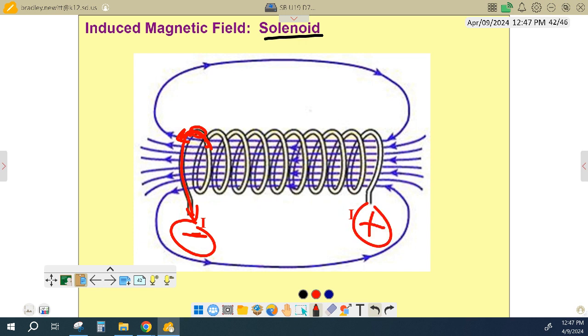All right. So this is one of the things we're going to look at today when you do the solenoid with the slinky. You need to think about what direction is the magnetic field that you're producing. How's it moving through that coil? But again, we can actually produce a fairly strong magnetic field in between there because everything's all pointing the same direction. It's all adding together.